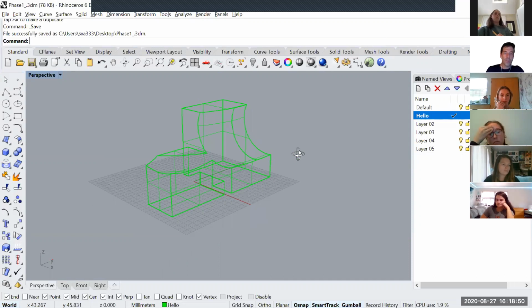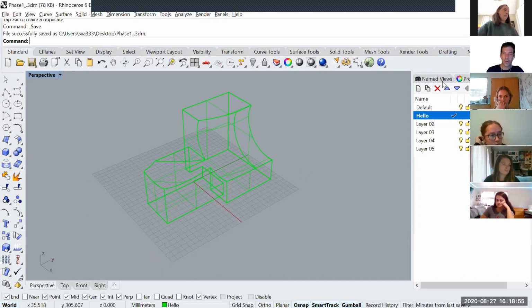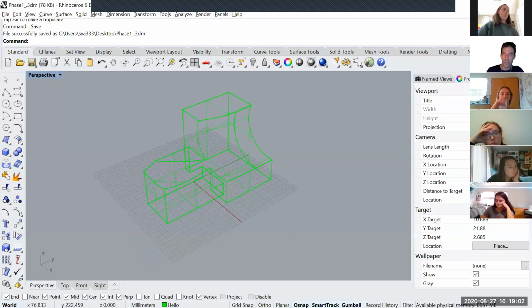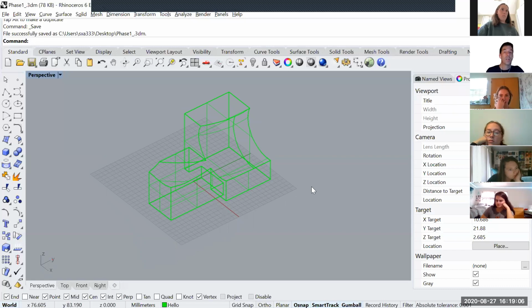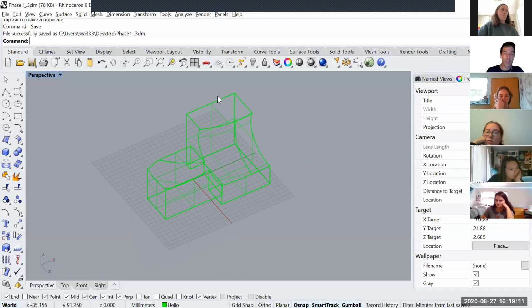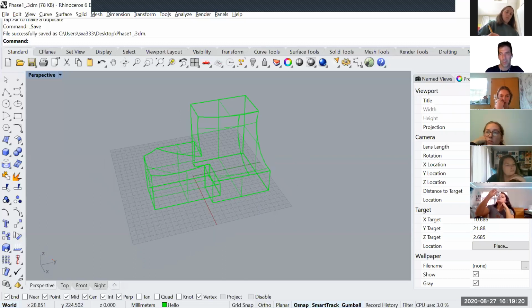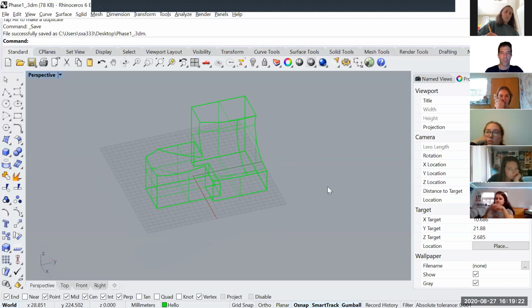We need to find a view that we like. One of the views that we're going to be asking for is actually the axonometric. So if we don't select anything, we can go to properties, and under projection, we can take this to parallel view. This is an isometric or axonometric, meaning that this line and this line that are parallel in the object are parallel in the view as well. We can go back to perspective as well if you want.